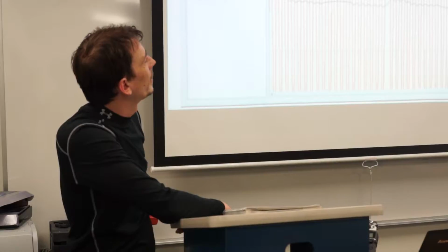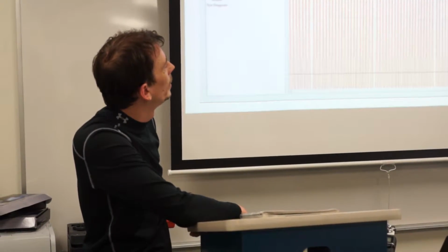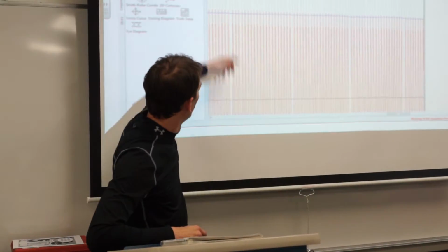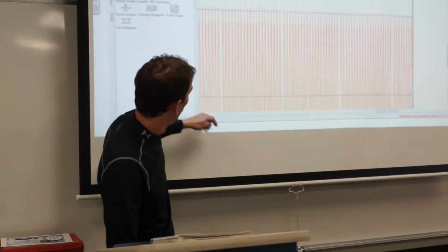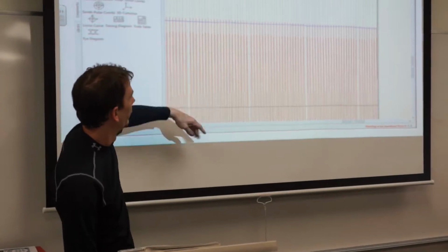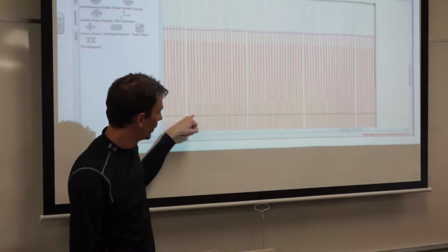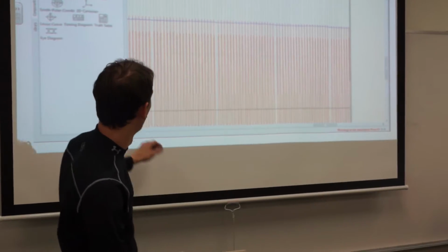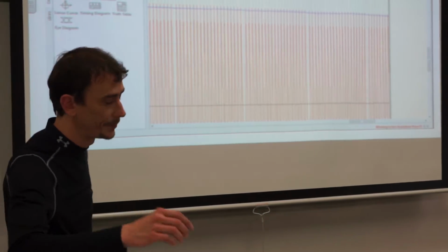I think maybe the next slide shows it getting smoother. What this is, ignore the blue line at the top. This is a bigger scale drawing. This is our 0.5 from our comparator. This shows you the relative scale of what the DC does in fact look like compared to the 0.5 all over the place. It's pretty clean, it's pretty straight, and at this point you can see how it's leveled off into a straight DC voltage.